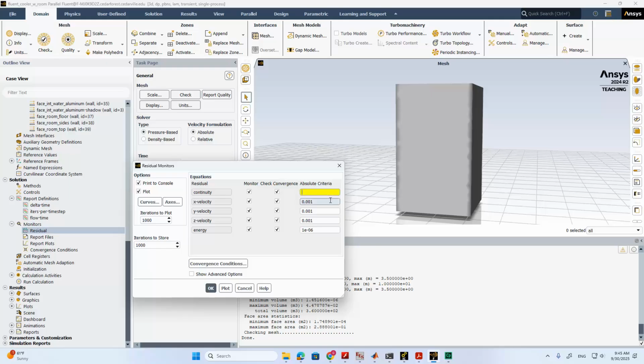So here, one danger is that this number is too big, so even if you still do not have good enough results, Fluent stops the iterations. So it's probably good to set a pretty small number for the continuity equation. Just make sure that Fluent keeps iterating, okay. In fact, you can always manually stop its iterations. So don't worry that it will do the calculation without termination. Okay.